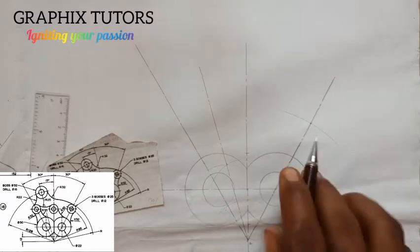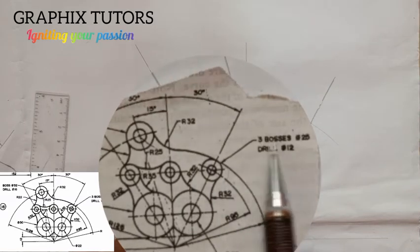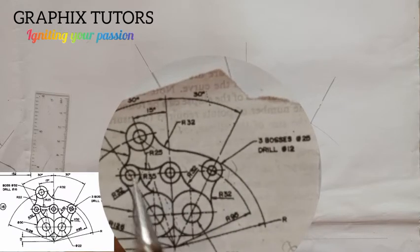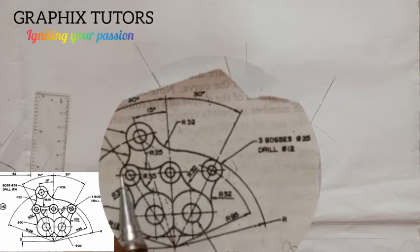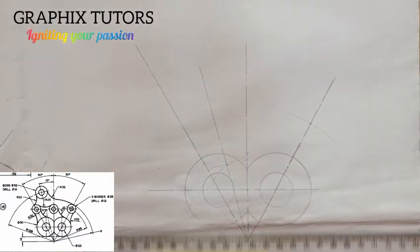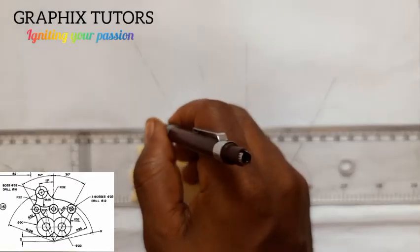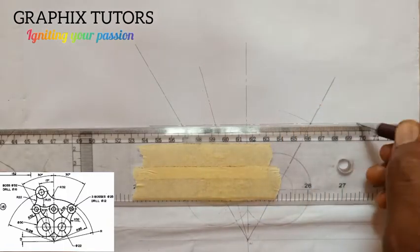So at that center line, before I draw anything, we know that the radius of this circle here is given to be, we are told 3 bosses, diameter 25. So this is 1, this is 2, and this is 3. That's what I mean by the 3 bosses. But these other 2 circles are on a line that is drawn straight from this point. So if I take my T-square, I'll take it to that point, and I'll draw a line this way. That's a center line. So this will be long, short, long, short, long, short, and so on. So this is where I'm going to draw.